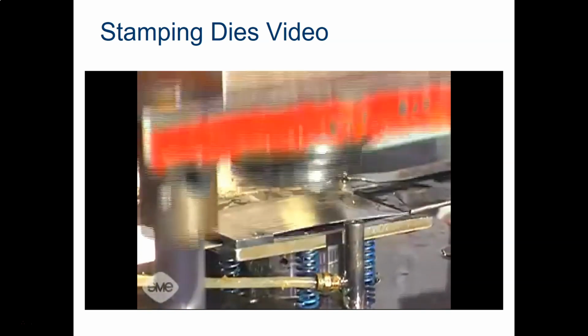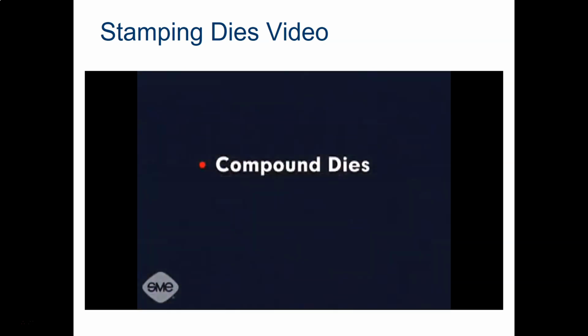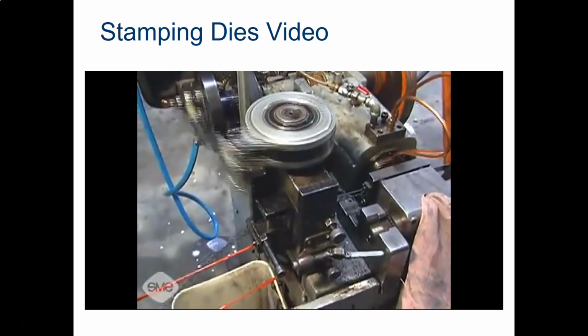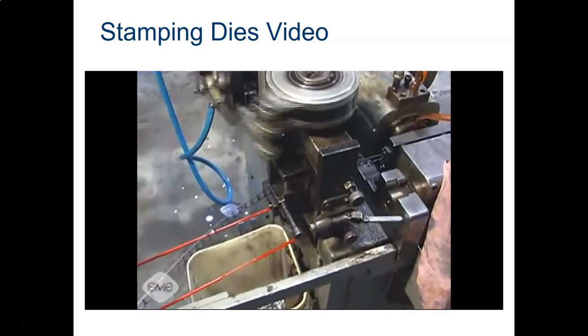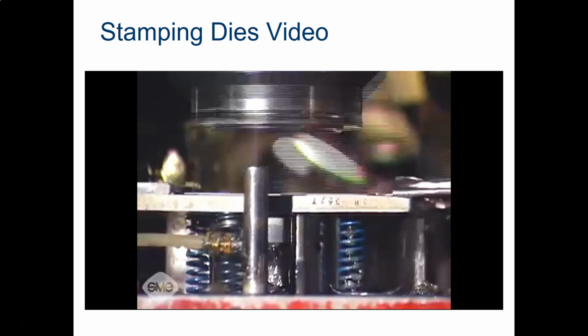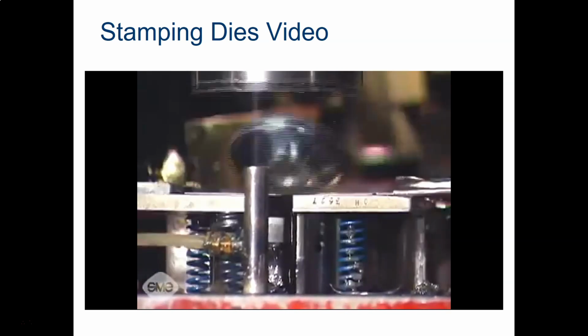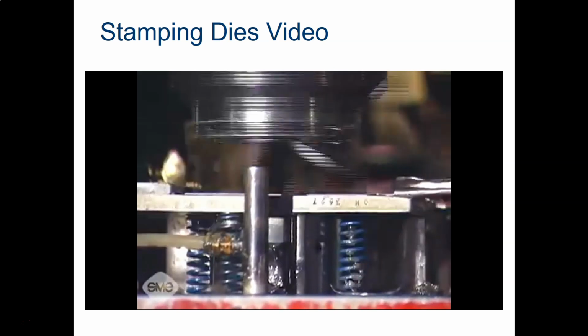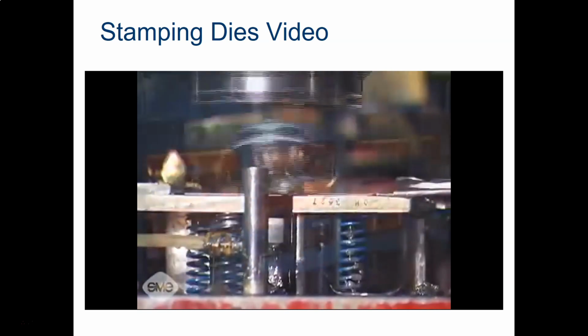Dies used in single station operations can be either compound dies or combination dies. Compound dies are press tools in which only cutting operations are done, usually blanking and hole punching. Combination dies are press tools in which a cutting operation, usually blanking, is combined with shaping or forming operations.